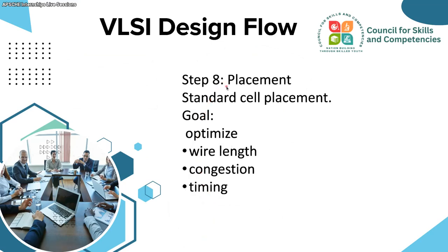Next comes the placement. So you will be having a standard cell, a cell like structure, and inside that you can have the gates. So they will place these cells. How to place, we have to optimize the wire length, congestion and the timings, because when you give the clock pulse, all the things we have to keep in an optimized way. So that is where step 8 comes in, the placement.